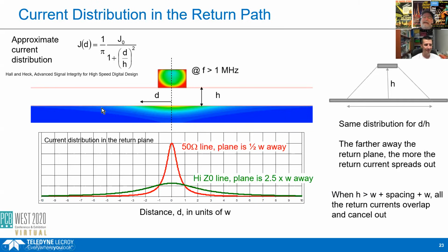If, however, I do anything to screw up this return path so that the return current is not in this region, like I take all of this conductor and I move it over here and I make it a pin in a connector, or a lead in a package, or I put a gap underneath here and I force this return current to flow over here, I have pulled that return current far away. I've created more inductance in that return path. Anything I do other than this region for the return current, I am going to increase the inductance in the return path, and that is going to cause voltage noise in the return path.